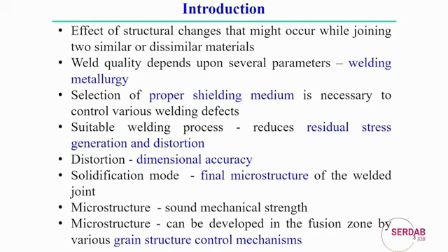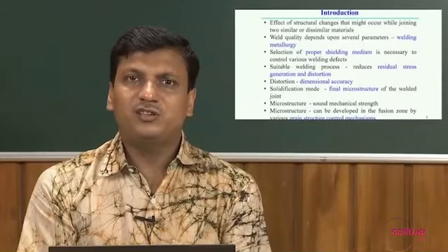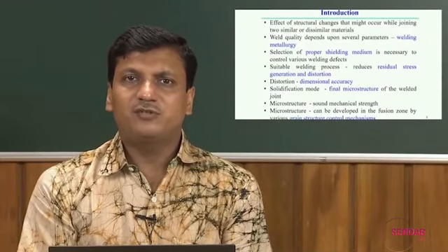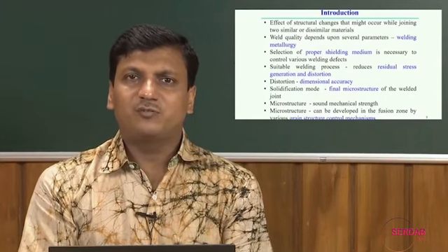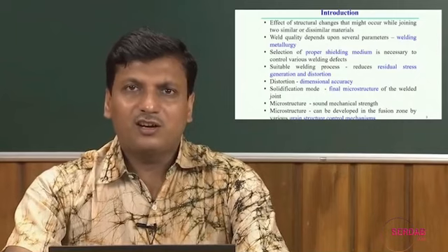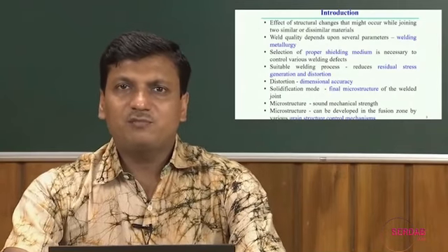Anyway, in fusion welding processes it is always subjected to some amount of residual stress and distortion. We cannot avoid this. What we can do is try to reduce the amount of residual stress and distortion, or if the residual stress is beneficial to some extent, try to maximize that component, but in most cases residual stress is not favored in the life of the weld joint.